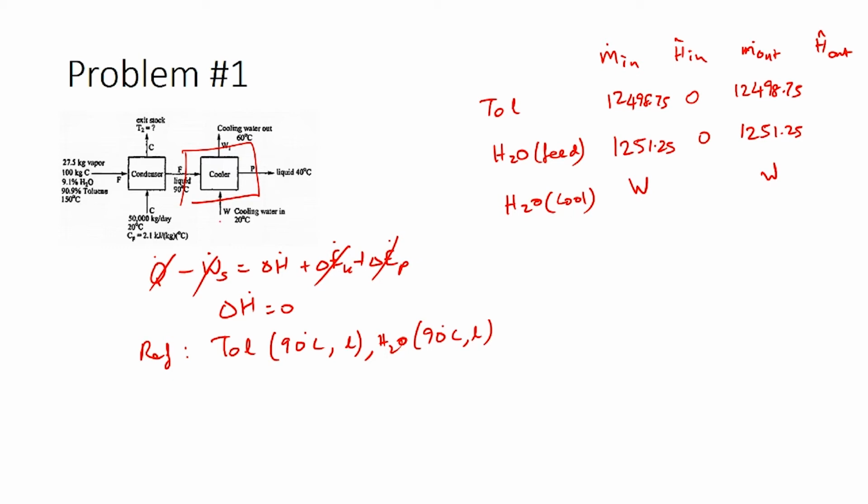So, the stream where water is entering as the cooling water would have some enthalpy difference from the reference state. So would the other streams. So, we would have to calculate 4 different enthalpies here. However, there is no phase change here, so we would not have to build any hypothetical paths, we just have to account for change in temperatures.